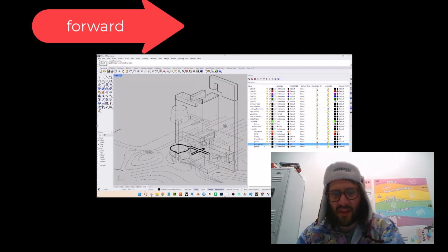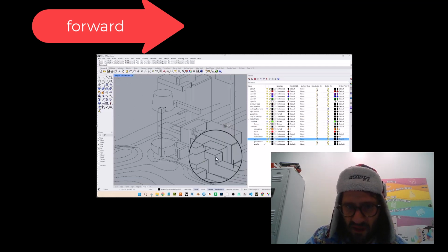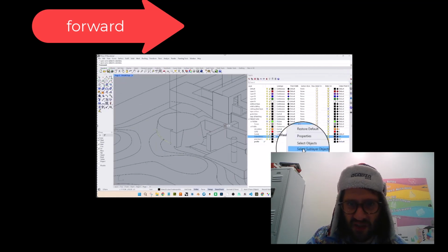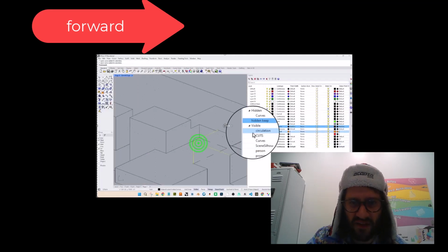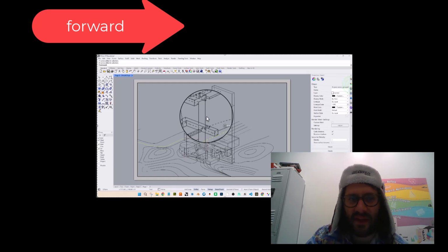Turn on the print preview, and then I'm just changing the line weights for cuts and hidden lines. A lot of hidden lines you don't need, so I made another layer called hidden lines to keep, or hidden keep. So then I'm just turning hidden line on and off, and being like, okay, I'll keep this one and move it over to this layer so that the hidden line would be invisible. I can't promise another tutorial here. This should help you get on the right track of how to make layers and clean up your axons to be a good line drawing. Hope that it helps you.